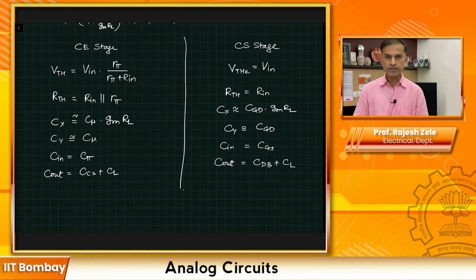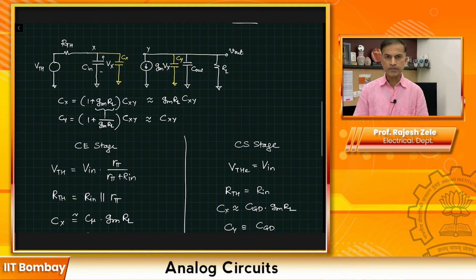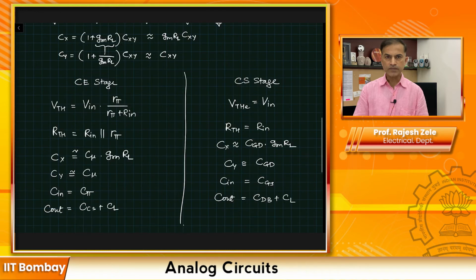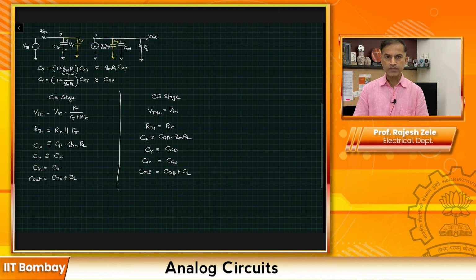What we are trying to do is use a common circuit for both the BJT as well as the MOSFET amplifier so that we don't have to do the analysis again and again. And this draws out the similarities between the two circuits. There are only two nodes in the circuit, node X and node Y, and you are seeing a resistance and a capacitance to ground from those nodes. So using this, we can quickly figure out the poles. There will be two poles.